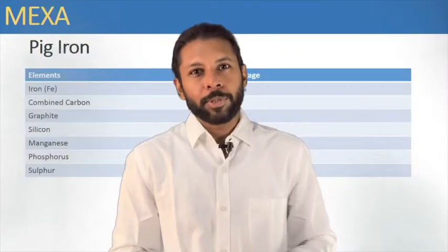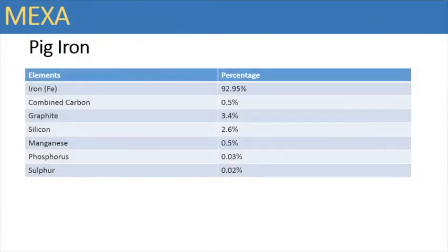The iron which is produced from this oxidation reduction action falls to the furnace bottom, melting as it falls and taking into solution carbon, sulfur, manganese, phosphorus, etc. When tapped, the molten iron runs from the furnace through sand channels into sand pig beds, hence the name pig iron. Pig iron is very brittle and has little use. An analysis of a sample is shown.